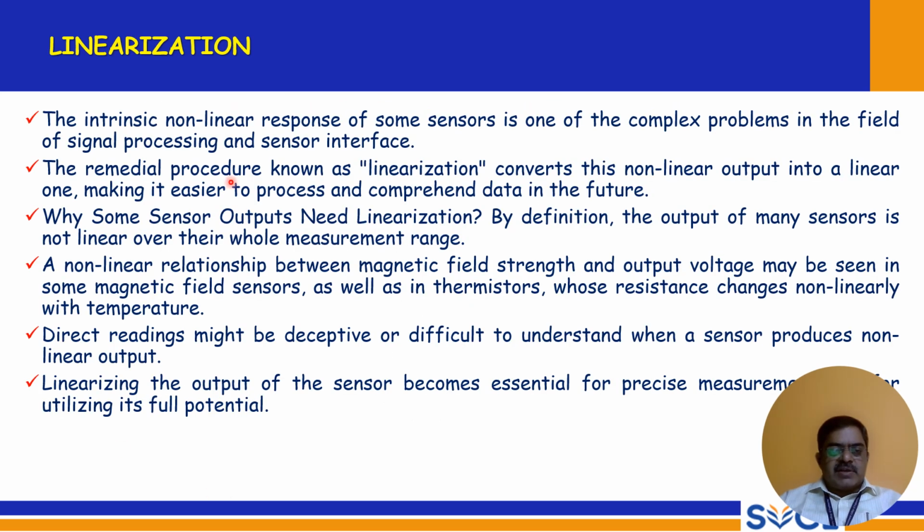Next is linearization. The intrinsic nonlinear response of some sensors is one of the complex problems in the field of signal processing and sensor interface. The remedial procedure known as linearization converts nonlinear output into a linear one, making it easier to process and comprehend data in the future. So linearization is such an important process. Why do some sensor outputs need linearization?